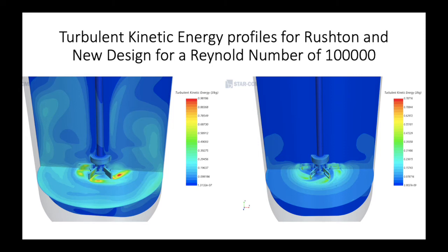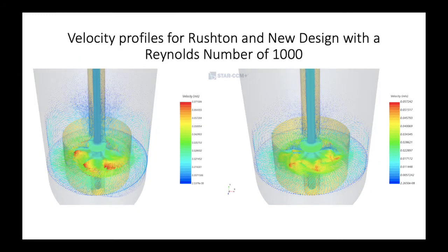However, the values are again higher for the Rushton turbine as a result of the higher power transmitted to the fluid. As is to be expected, the highest values of velocity are obtained on the edge of the impeller blades, as the rotational speed is the same on it, but due to the distance from the center, the tip speed is higher. The no-slip condition can also be detailed from the velocity patterns, as the darkest tones of blue are located near the walls, including the shaft.